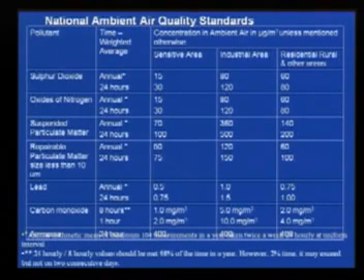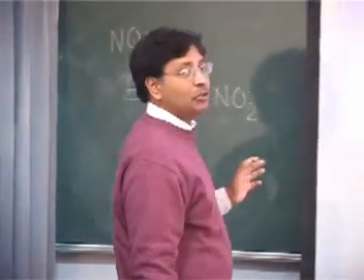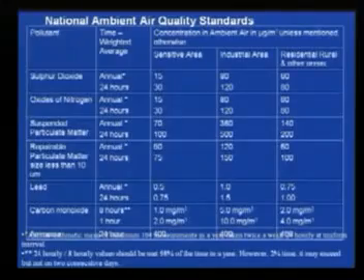This is somewhat higher. And then it will go on to specify what sample will constitute an annual sample. So you can't say, I've taken 20 measurements, sir, this is my annual standard, it is exceeding that. No. We are talking law, we are talking legal terms: annual arithmetic mean of a minimum of 104 measurements in a year, not all the measurements you have taken in January, February, March, but in a year, taken twice a week, 24 hourly, at a uniform interval. You can do more than this, there's no problem, but we have to be very clear: the 24 hourly and 8 hourly values should be met 98% of the time.